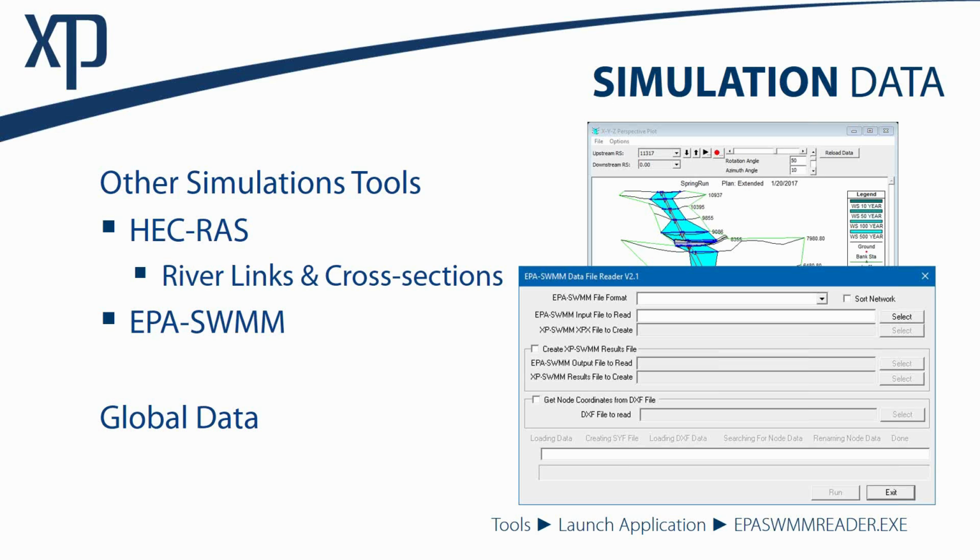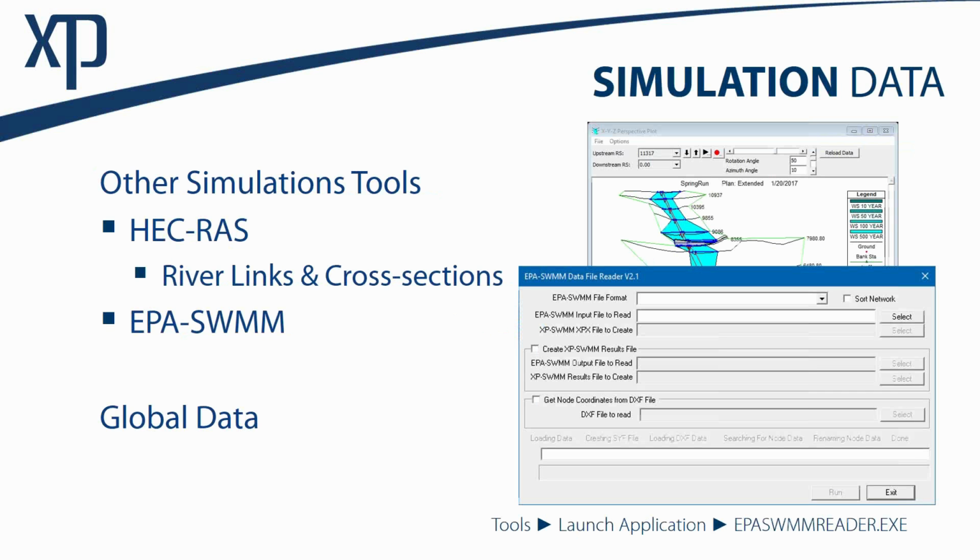You can share elements out into a template, or you can share that out to an XPX format that can be reused, or you can merge that information. Merging isn't just for taking nodes and links and bringing it into your model. You can bring in job specifications, you can bring in other global data to your model. Just want you to be aware of those different methods and go from there.